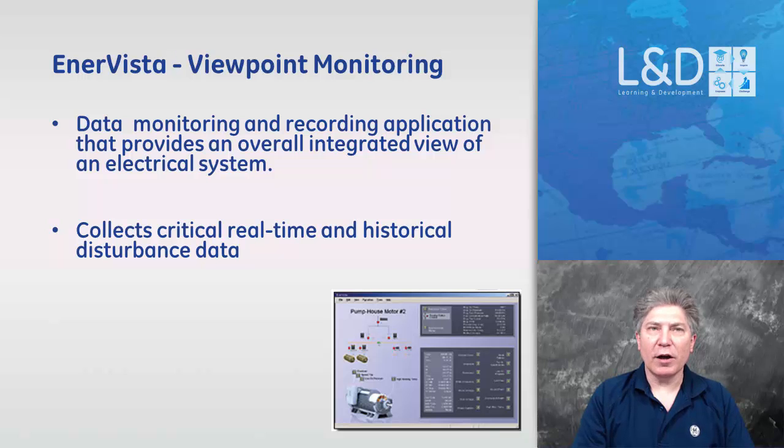We can control and monitor the status of switches and breakers. We can set up an annunciator panel to notify the operator that an abnormal condition has occurred and send the status to 5 email addresses. There's a data logger with a 1-second resolution built into it. And it also records its own system events in the event that something goes wrong within the system itself.